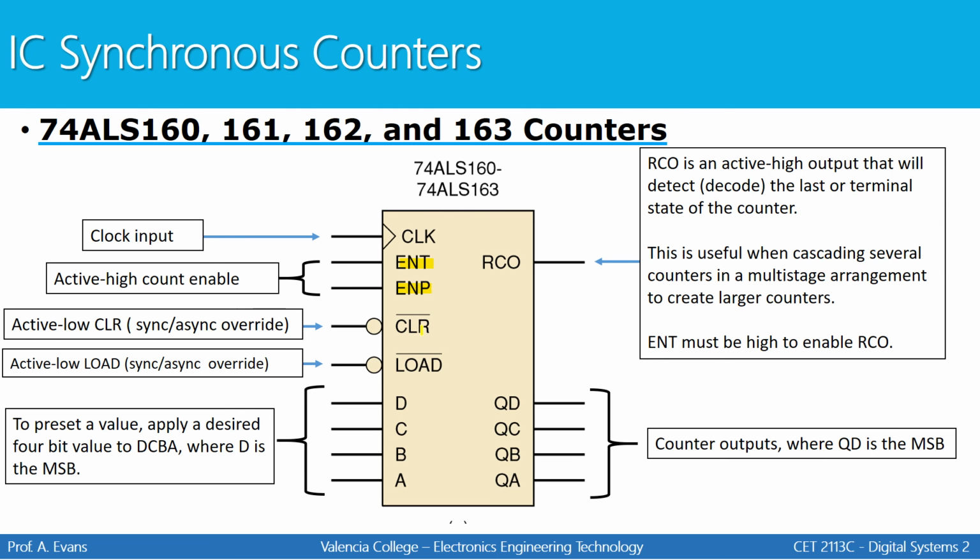You have your clear. It's an active low input. And depending on the part number, this will either be synchronous or asynchronous. And I'll show you a function table where we can determine which part numbers have which function. So this could be synchronous or asynchronous, which will matter when you're drawing a waveform. We have an active low load. Depending on your part number, this can also be synchronous or asynchronous. I'll show you the function table in a minute to know which way this one is going to work.